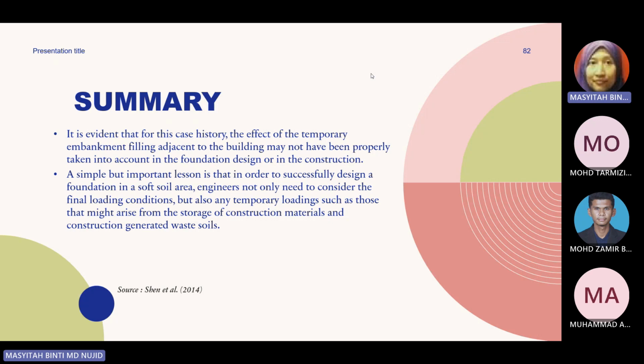Then they want to know where the cause of the building failure is. So the event has already happened, and we cannot dig up the structure again. So what they do is estimate or run a simulation to predict whether the cause is the soil, bearing capacity, low strength, or the structure. This problem involves interaction between soil and structure. So when they did the numerical simulations, they found the problem came from the structure itself, the structure capacity. The structure capacity here was triggered by the moment resulting from stresses induced by the north side and also the south side of the construction activities.